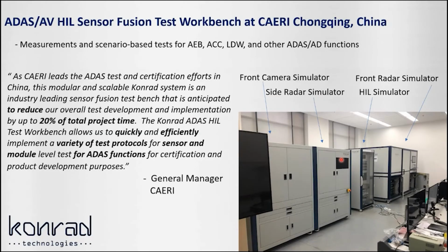So in this particular deployment in China for one of our customers, what we basically did is set up this particular flavor for HiL testing with the front radar, the side radar and the camera simulator. And this was the first step leading towards being able to test not only the sensors, but the sensor with the software ECU for ADAS, and moving up to level 5 was the intent. Okay. So this is a deployed version, and we have several of these around the globe. Next slide, please.